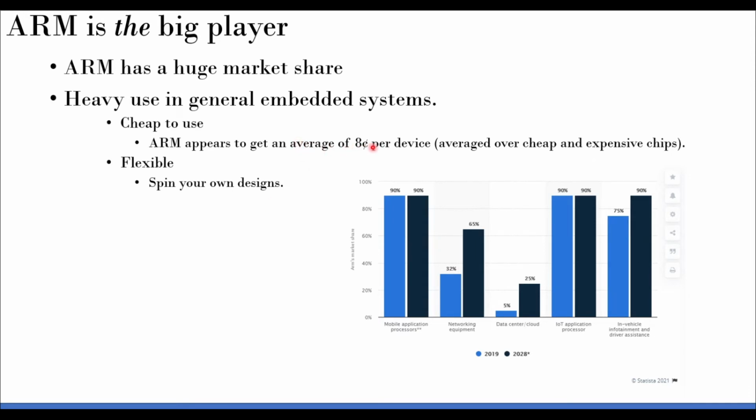That's very cheap. The board that I am going to give you to take home is ARM processor based, and is manufactured by NXP, as I said. The board is popularly known as the Freedom Board, KL25Z is the number of the board. It has a Cortex-M0 Plus processor, which is a 32-bit processor. It has around 128 KB of RAM, and an accelerometer and gyroscope built in.